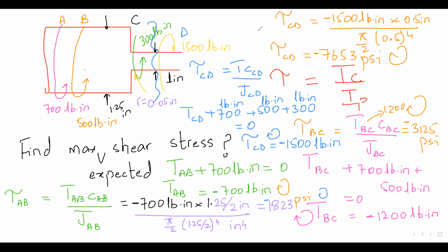I know. But here comes my concern. Let us say by cutting at another portion, I get even more shear stress or more torque, but that's not the point. I have to get the torque right, which is happening near or right at the stress concentration. Just finding the maximum torque or maximum average shear stress is not the concern. So when I am cutting from here and I'm getting a shear stress of 1823, just imagine if I had got 10,000. I wouldn't have used this 10,000 because this AB concerns here, whereas my stress concentration is happening on this region. I have to get hold of every shear stress for this region. But the question doesn't ask for the maximum shear stress in the stress concentration region.